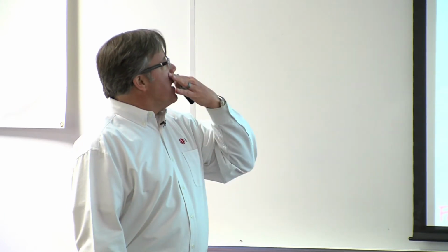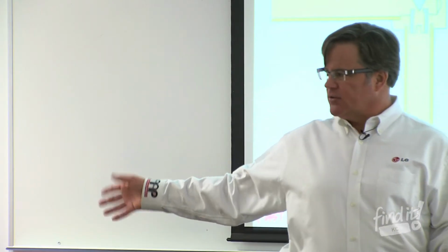Electronic expansion valves are in all the units. The only reason I talk about this is because fundamentally VRF controls temperature in the space differently than any other system that we're all used to. Every other system that we're used to, if your space gets too cold, a signal gets sent to a compressor or something outside, it kicks on, runs full speed, and floods that coil, air blows over it until the temperature gets better in the space, right?